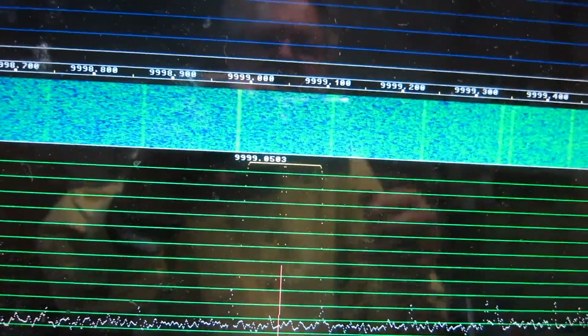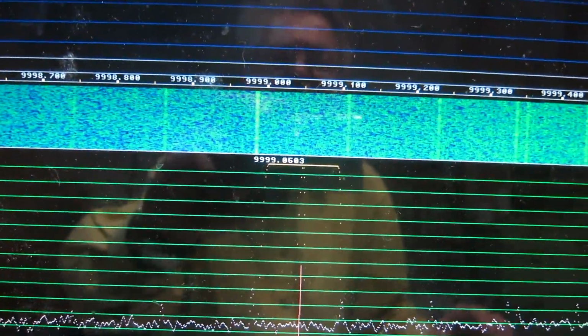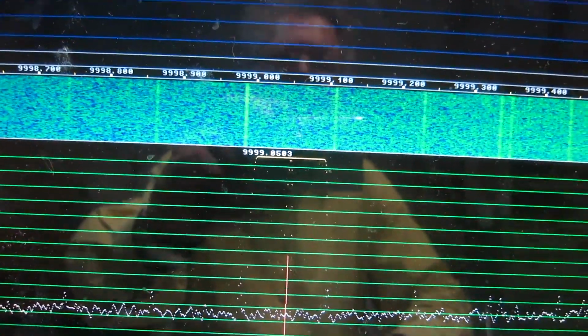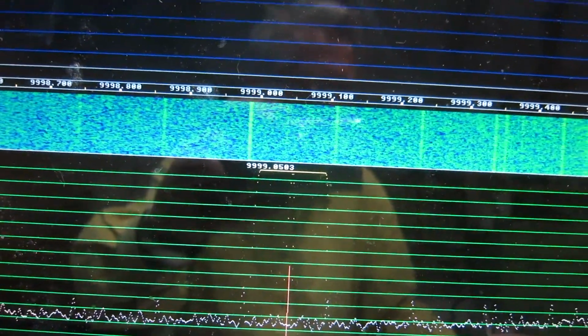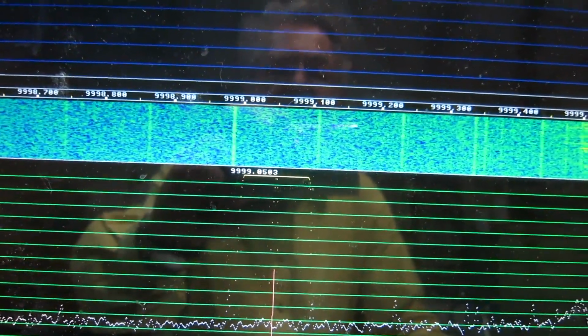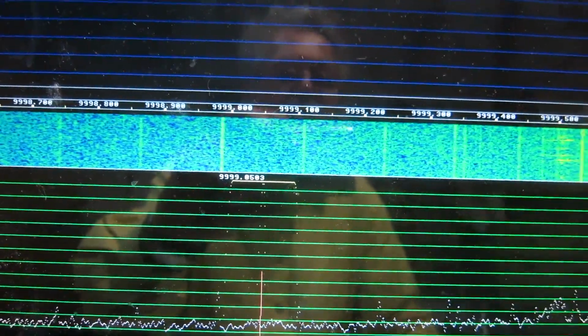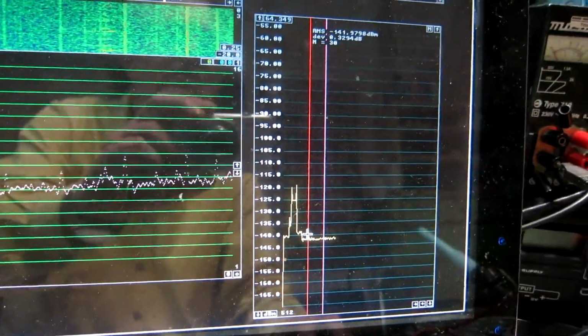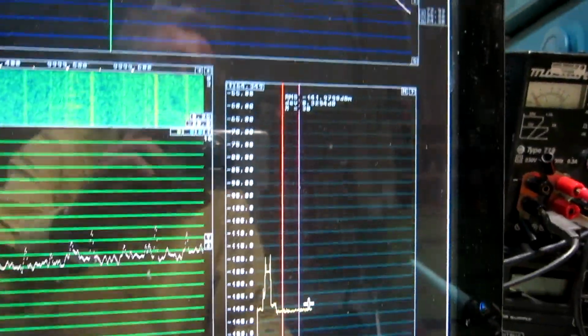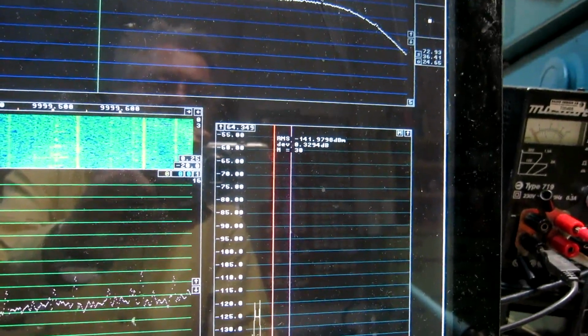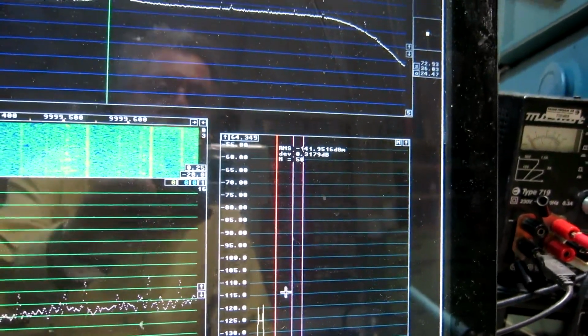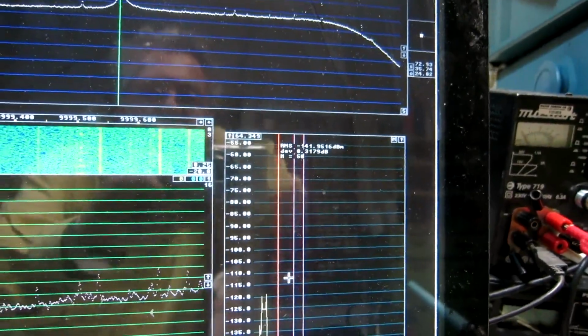Here the frequency separation is 950 Hz. I want to avoid the overtones of the mains frequency, the odd overtones. And the bandwidth is 100 Hz, and the noise I see is minus 141 or minus 142. No. Well, minus 142.